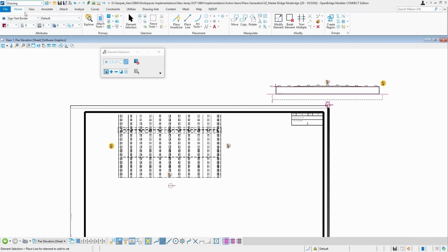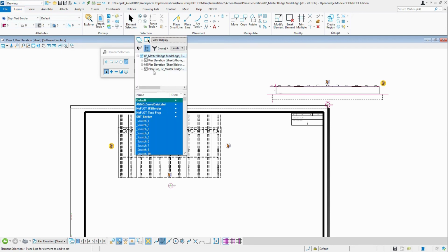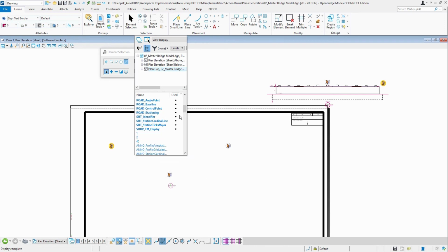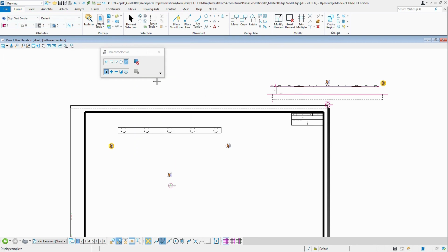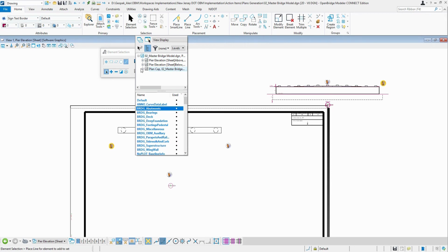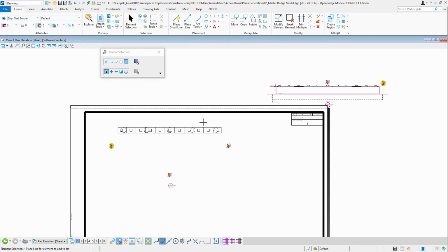Do the drawing itself, and just adjust the levels too. Blank up, reference file, and then just display the levels that I want to see. And so, as simple as it could be. So I just showed you two methodologies, element by element, or just with the level display on reference files to see what elements I want to see. Maybe that should be enough there.